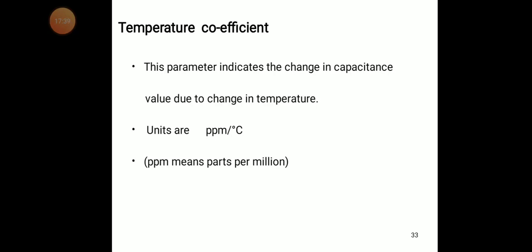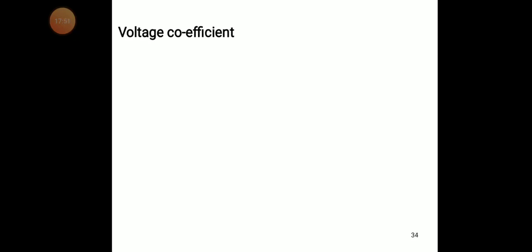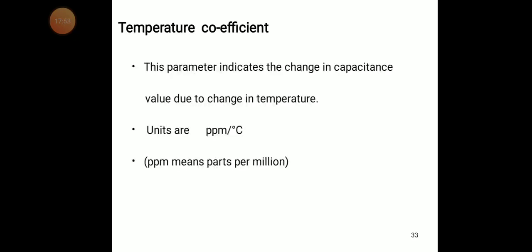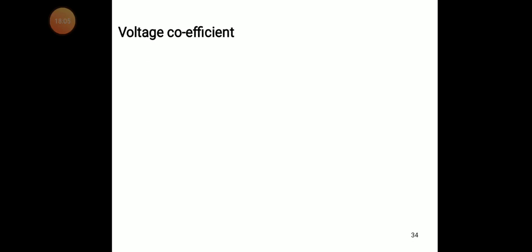This is also very important. If the environment is a temperature-sensitive area, we also consider this change in value, that is the temperature coefficient. So this is another important coefficient. This parameter indicates the change in the capacitance value due to change in the temperature.